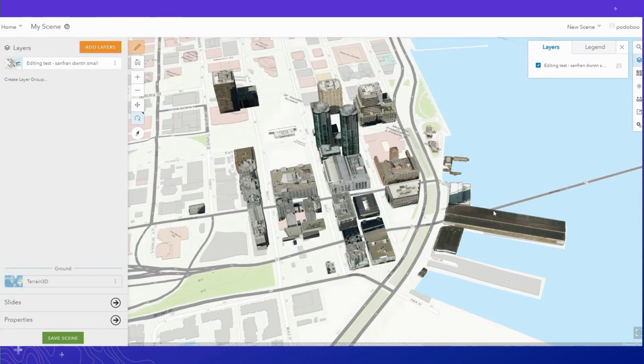Before I run the next video, I'm going to quickly explain what it does. First, the service is opened in ArcGIS Online, and we can see the pop-up data. Then we go back to Pro and view the same pop-up details. Next, we run the add-in we created and verify that the data has changed. Then we refresh ArcGIS Online and see the changes in the pop-up. The pop-up information is pulled from the associated feature layer, so we will be able to see the updates in ArcGIS Online immediately. If you were to modify geometries instead of attributes, you would need to recreate the cache in order to show the changes.